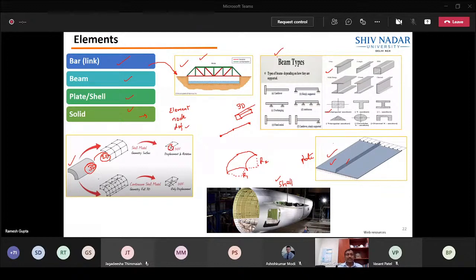There is also a very interesting case. If I model the same thing, I can use either the degenerated form in 2D, or I can model the same as a 3-dimensional one. If I bring out one element, you can see clearly that one is a 3D element in shape and the other is a 2D element in shape. The degrees of freedom you need to understand here are displacements and rotations, whereas in the case of 3D, it is only displacement degrees of freedom.